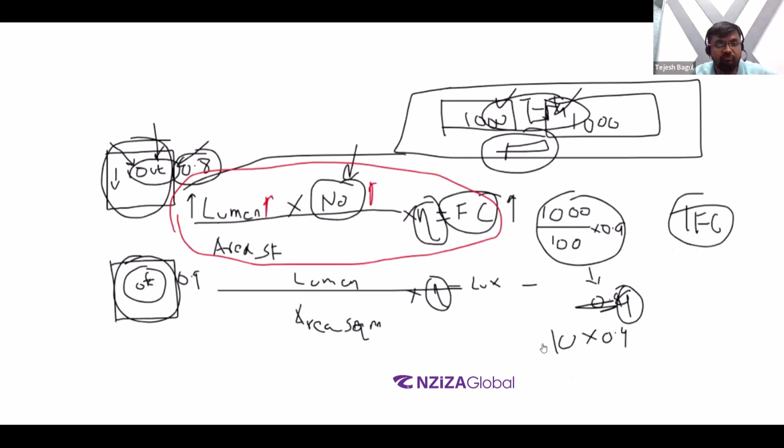Because if you have worked in the real world, you will see for a given manufacturer's catalog, there will be different lumen outputs. Of course, that lumen output will correspond with the wattage as well, just like we had something like 96 watts at 86 lumens per watt in our given light fixture in the Revit model.